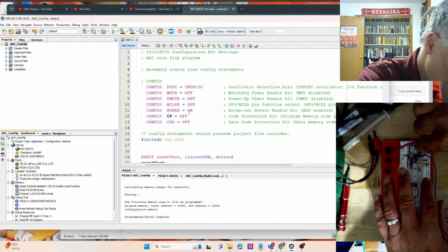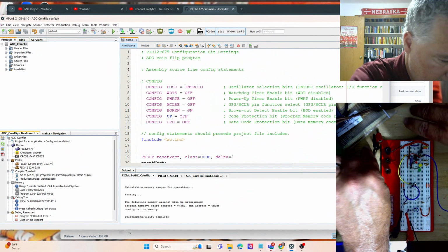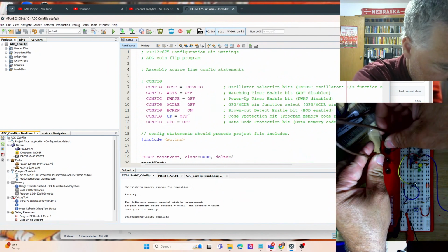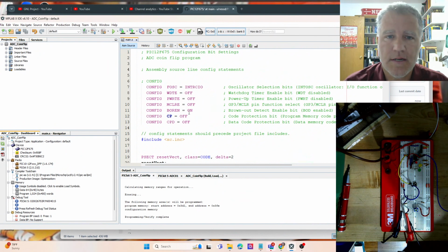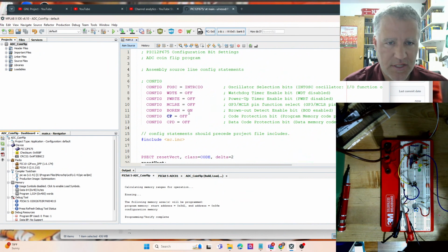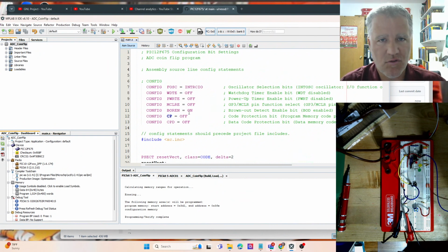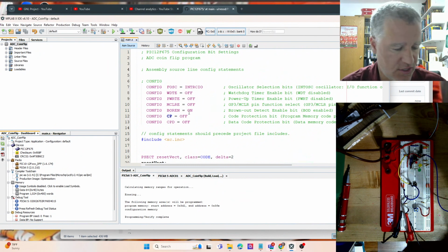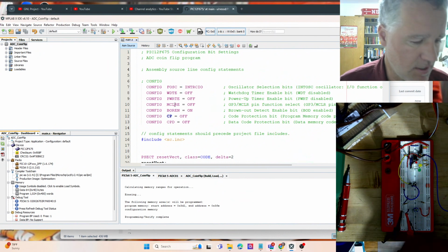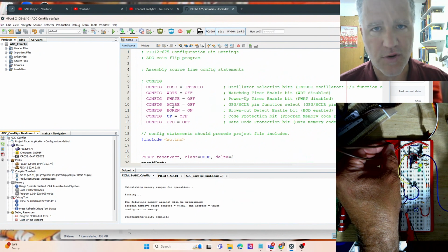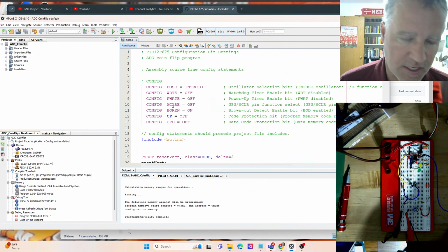All looks good. So now we will unhook this and hook up the power. Again, whenever I'm working with the analog to digital or the comparator, I like to power the chip when we write to it with the PIC12F675 programmer, but then I don't like to power that, and it doesn't even work if it's connected for the normal operation of the chip. So we're always flip-flopping between the PIC12F675 programmer and then some external source, and this is just plugged right into a USB that's plugged into the wall.